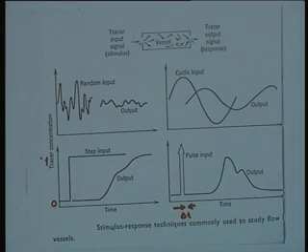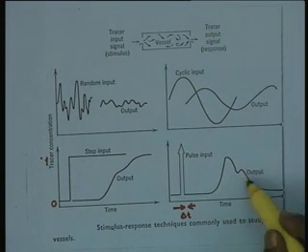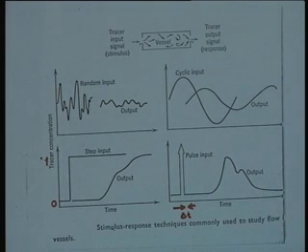Theoretically the product in a plug flow reactor must come out exactly after the residence time of the feed stream, but very often, because of deviation from ideality of plug flow behavior, it might come out in a slightly broad zone. Some of you must have done chromatographic experiments, where very often broadening of the output is one of the major problems.